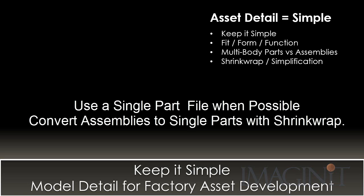You also want to represent the asset using a single Inventor part file instead of a large assembly. Often, you have to convert a large assembly into a single part file, and there's a number of tools built into Inventor that allow you to do that, specifically the Shrinkwrap command and the Inventor simplification tools.